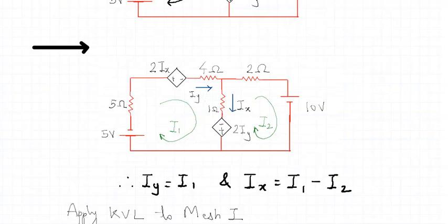You choose any point where you will start applying your KVL, and following the reference point, you go in a clockwise direction following the current direction that you have assigned and complete the KVL equation. Yesterday we also discussed the rise in the voltage and the fall in the voltage, which helps us to assign the polarities of the voltages that we consider when we apply KVL.